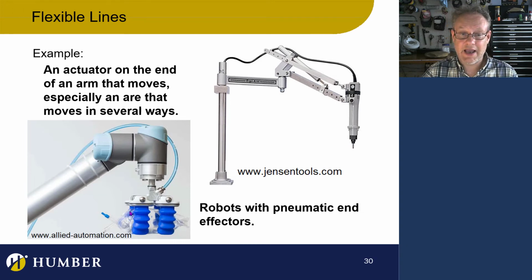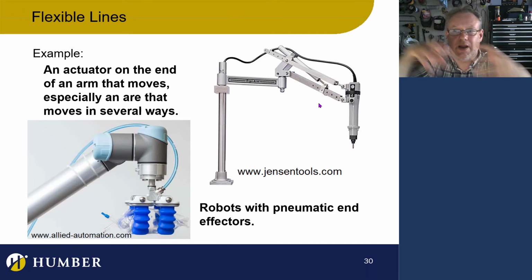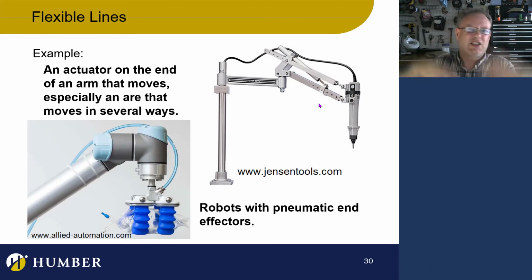Now, this one is just a vacuum system. It looks like these are these cool little grippers, working in an environment where it's just picking up little pieces of plastic, so there's no chance that this line is going to get into something and get cut. But this is more of a machine that's operating. It looks like it's drilling stuff, and you need maybe a more flexible, tougher line there. So with your flexible lines, you have to think about what material they're going to be made of.